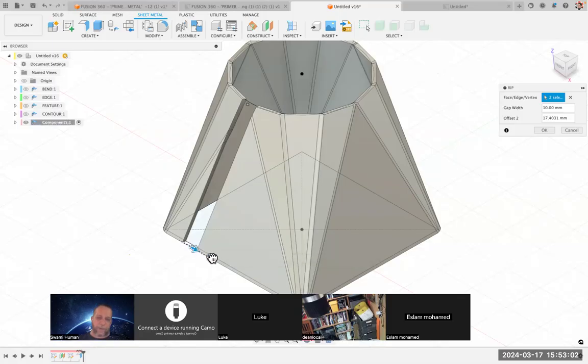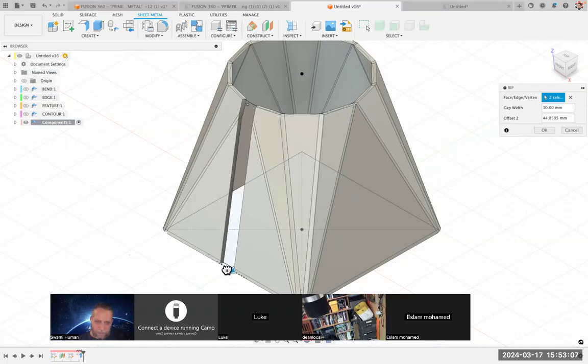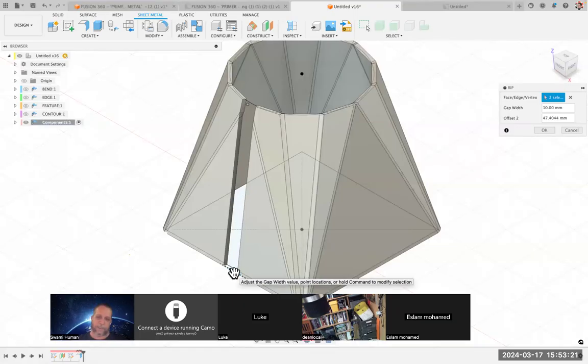So the downside with this approach, can I drag it and find the midpoint again? I'm not sure if that's finding the midpoint. Once I've dragged it one time, can I get back to the midpoint? I don't think it's recognizing the midpoint because it doesn't really know the midpoint. It just knows that offset distance. And that is the crux of the downside of this. It's quick and easy, but if I were to change these profiles or this geometry in some way that it's not all lined up nice and symmetric, then that line might not be straight down the way I really wanted it.